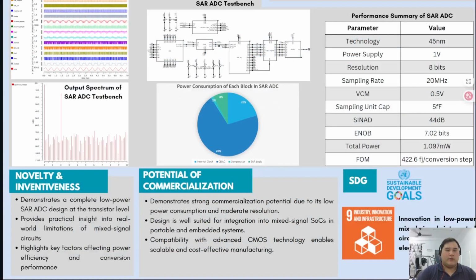Now I'm going to proceed with the novelty and inventiveness part of the project. This demonstrates a complete low-power SAR ADC designed and verified at the transistor level, providing a realistic implementation beyond behavioral modeling. The project offers practical insight into real-world limitations of mixed-signal circuits, including non-ideal switching behavior and power-related constraints. By analyzing the circuit operation in detail, key factors affecting power efficiency and performance are identified and clearly linked to measured metrics such as power consumption, ENOB, and sampling rate.